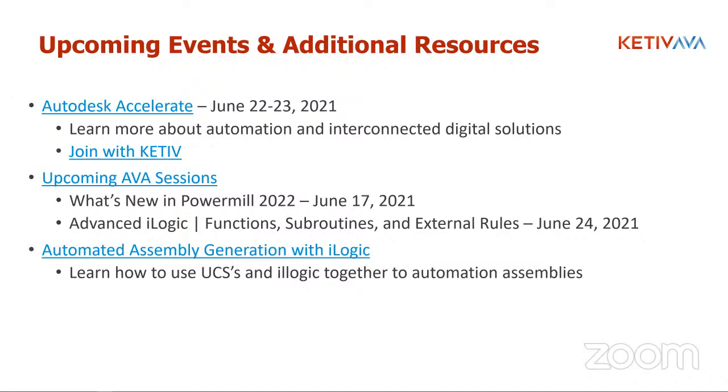And then finally, this is a topic that came up that I do think is really interesting. We did an AVA recently about automating assemblies. So not necessarily exclusively about UCSs, but iLogic does take advantage of and is aware of UCSs, similar to how it's aware of other named features or work features that you would use to help automate assemblies.